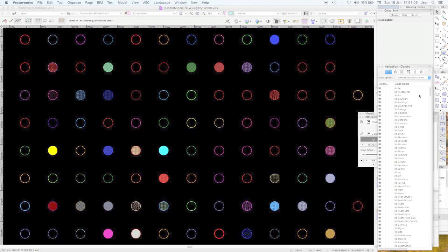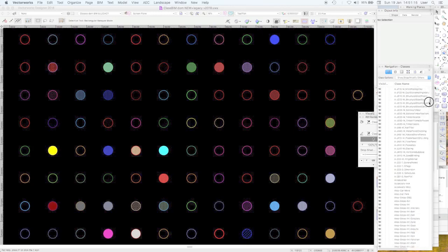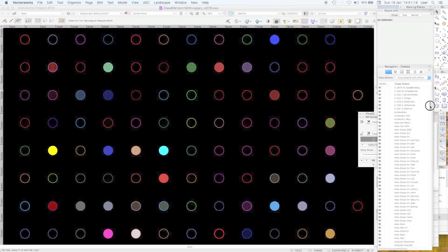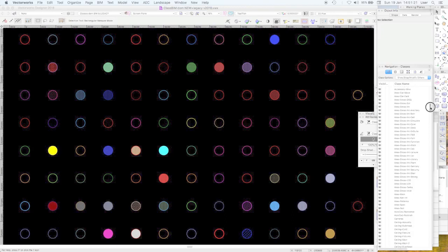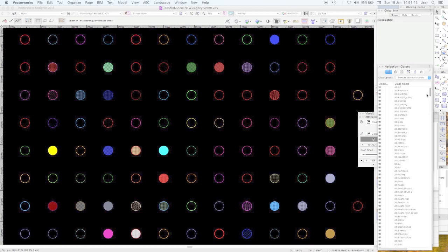I mean, okay, my layers here. I do separate my 3D and my 2D stuff. It's a bit of an obsession. But I do find that there are instances where if I'm in a view, I've drawn the 3D object in the same layer as a 2D representation of it, unless, of course, it's a hybrid symbol, but often it's not a hybrid symbol. So that's my justification for that. If I'm working in 3D, I use these classes which begin with the word 3D.